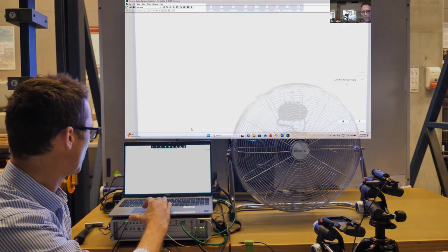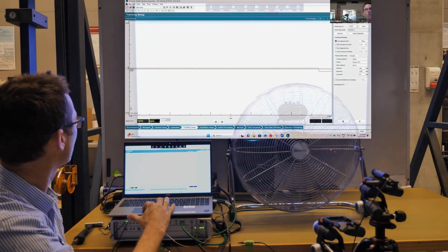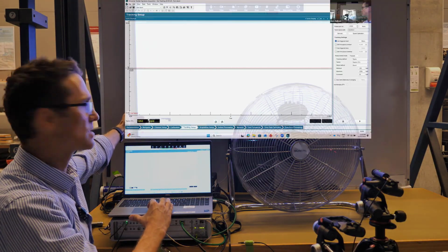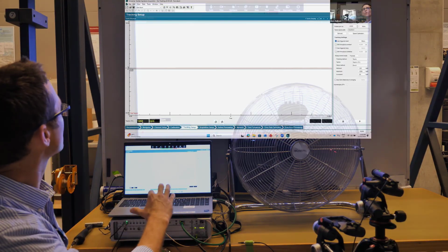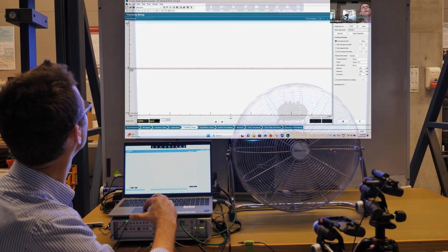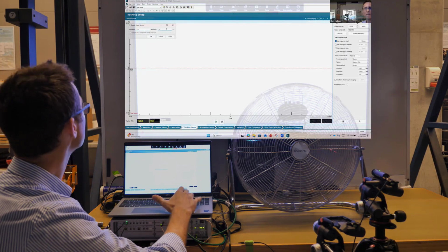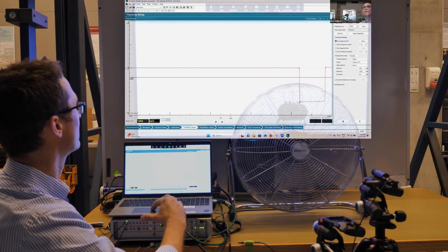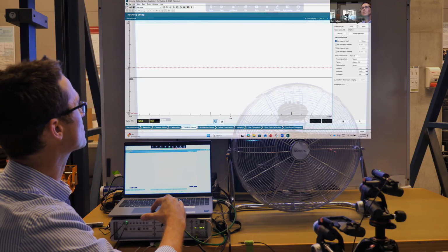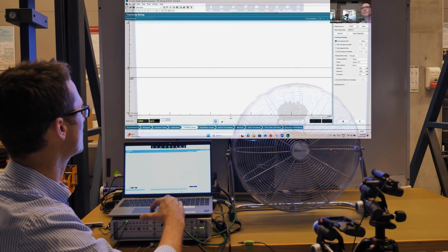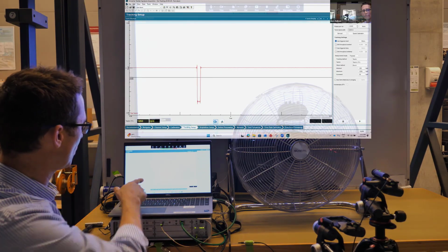If I jump into the tracking setup workbook, here you can see, I've got another screen up here, so maybe it's visible on this screen up here. As a result of the tachometer and the once per rev pulse that's generated every time that piece of retroreflective tape passes through the path of the beam from the tacho, I get a pulse in that signal here, which if I zoom out a little bit on the time axis, hopefully you'll be able to see those pulses passing through.